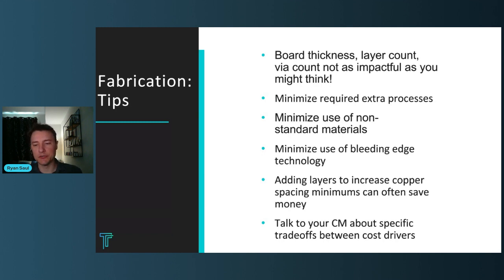Finally, and this is related to everything I've been saying here, avoid controlled dielectric custom stack-ups. Now, I would say as an engineer, I've talked to a lot of engineers about this, it feels better to design your own stack-up in many cases. You get to do your own impedance math. You get to design your trace dimensions such that everything works out, and you're just telling the fabricator, look, build it exactly like this, and everything's going to be great. And yet,